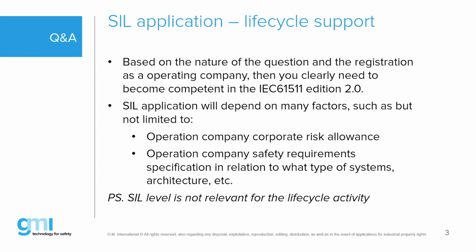Once you know you need some more risk reduction, then your operating company can maybe have a safety requirement specification. That means you have maybe your own template, your own way of describing your SRSs. They will explain in there what type of systems you are allowed to use. Maybe in some cases you will have to use hardwire logic or programmable logic or relay-based logic or whatever it is. There it will also be explained in your company what type of architectures you are allowed to use or not. So those are all kinds of items. In a generic question as you ask, I cannot really say more than I just said.